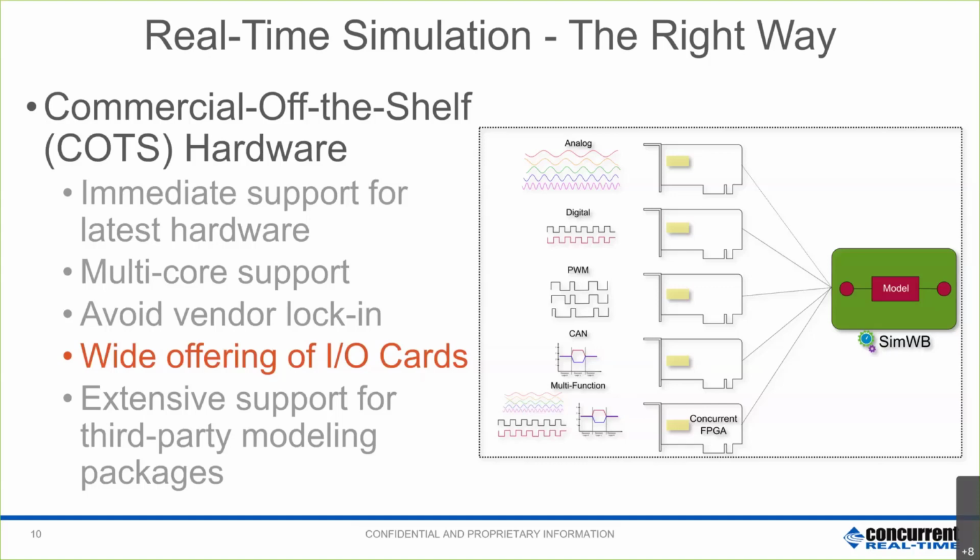Say in chassis development, you want to control a big hexapod from your model. Now you need a hardware interface for that to work. You can control this big hexapod using maybe an EtherCAT device or something like that. So how can your model talk to this device? You have to use this interface, the EtherCAT interface.